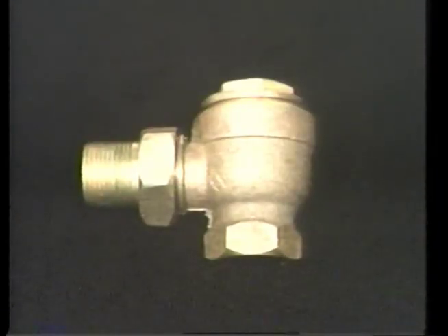All steam traps have some sort of mechanism to sense the presence of steam and stop its flow, while still allowing condensate and air to pass. Now, there are three basic ways of doing this. First, traps can respond to the temperature difference between steam, which is relatively hot, and condensate and air, which tend to be relatively cool. Steam traps that operate on this principle are called thermostatic traps. The most common thermostatic trap is the bellows trap.